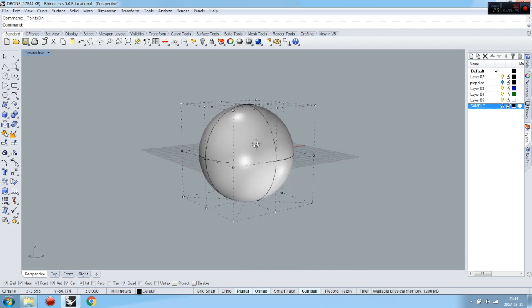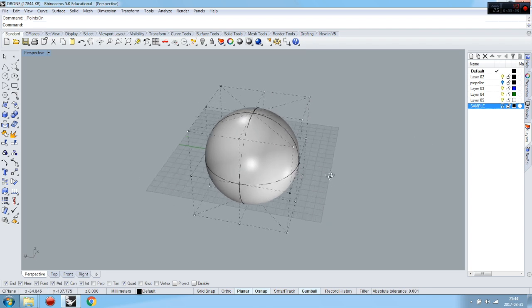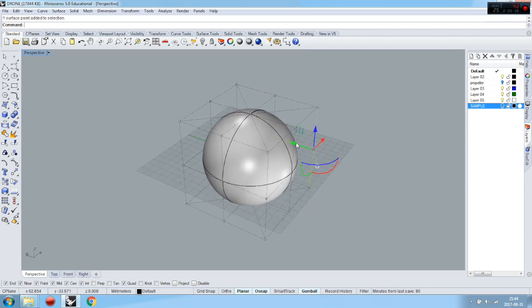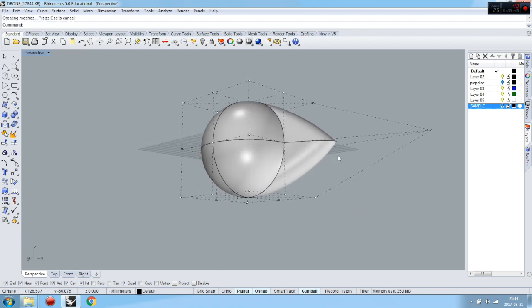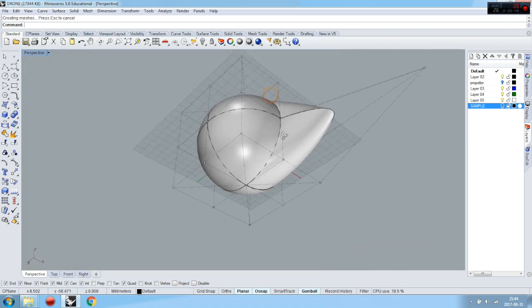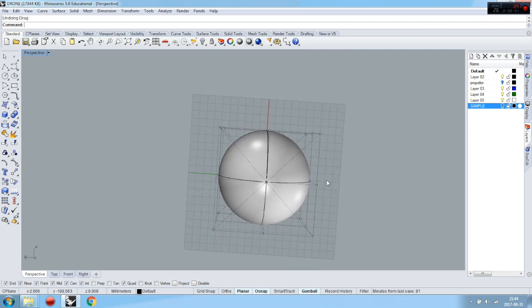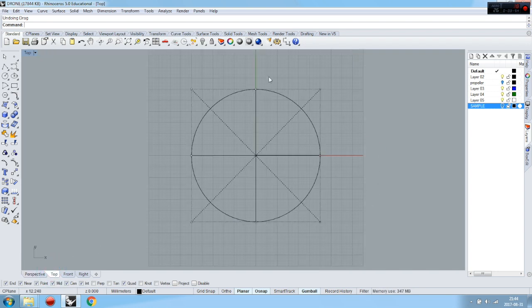our sphere is very simple right now. We need to rebuild these control points to play a little bit and get the shape we want, because if we, for example, move one point like so, it's not going to be very nice, and there are gonna be sharp edges like this, which we don't need. We need some more points, but at the same time we need to be symmetrical. So each quarter of the surface needs to fit 2 or 3 rows of your control points.